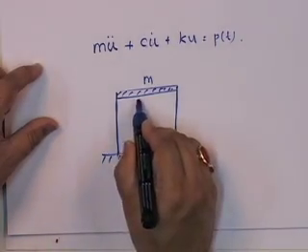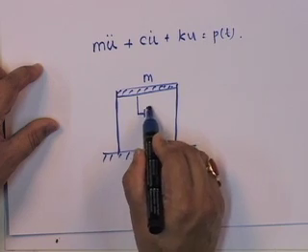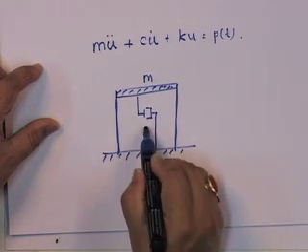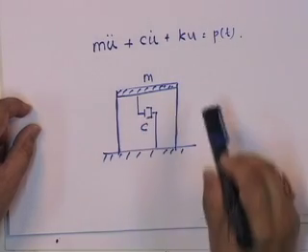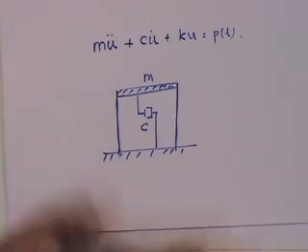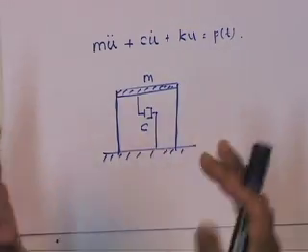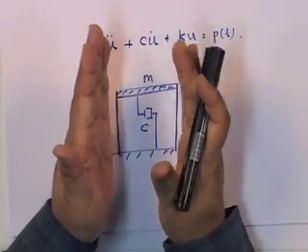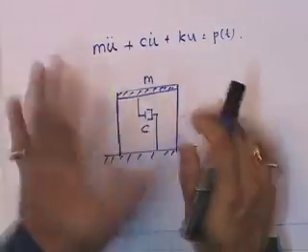What they said was that the energy loss in this system is actually modeled by a mechanical dashpot. Now, in reality this dashpot does not exist, because after all, have you ever seen a single story building with a dashpot in between? No, it is a single story building with columns, beams and the floor, etc.